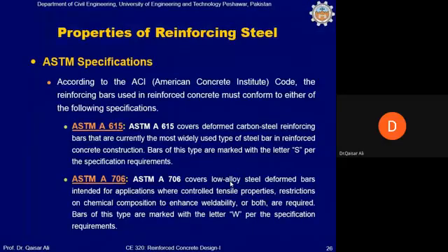This steel would have a set of properties, not one property, like its compressive strength, tensile strength, yield strength, ductility, its strain, and all these things. This set of properties is given a name, and this name is given by ASTM. For example, if it is ASTM A615, and you study ASTM A615, there will be a list of properties that a steel conforms to when it has the following properties. I hope you understand this now.